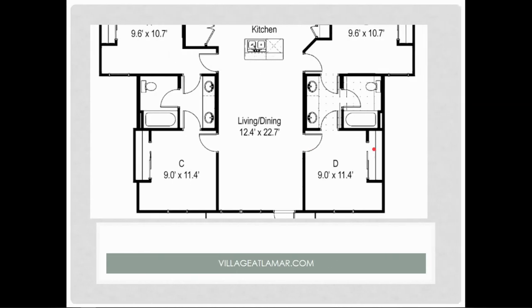The floor plan is pretty straightforward. It's also called a plan view. You can see, pretty simple. It's got some dimensions, 9 by 11. And then you can see where it has the doors cut out. This is sometimes called a Jack and Jill bathroom. It has 2 doors because it's shared between both bedrooms. And then this is one of a sliding door for a closet. Right? You can tell because the door is going back towards this way, and it doesn't have the swing as in the entrance into the door or into the bedroom.